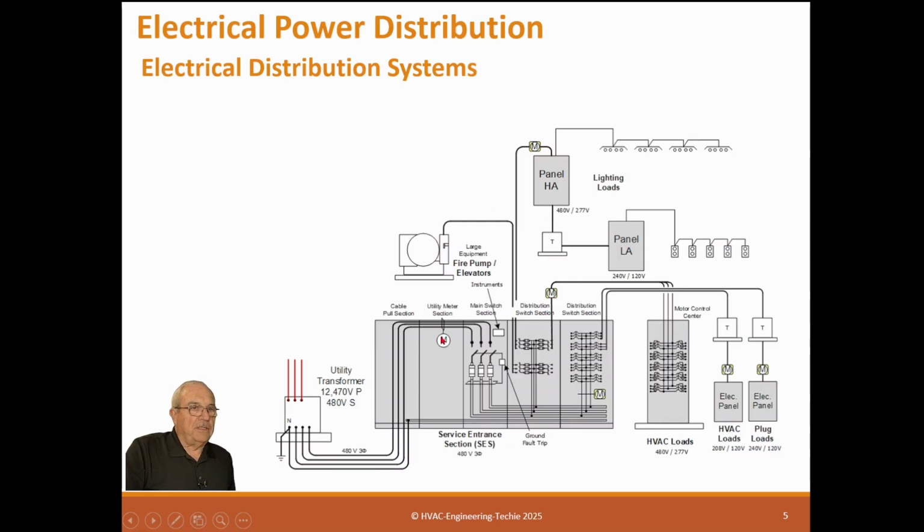This shows metering. So you can have the main meter from the utility. And you can also have sub-meters if you want to do energy conservation. If you want to try to save energy in your building, you're going to have one meter here for all the mechanical loads, and another meter here that's metering just these particular loads. And then you can have a meter here for the lighting. This meter would capture all the lighting. This would do all these HVAC loads.